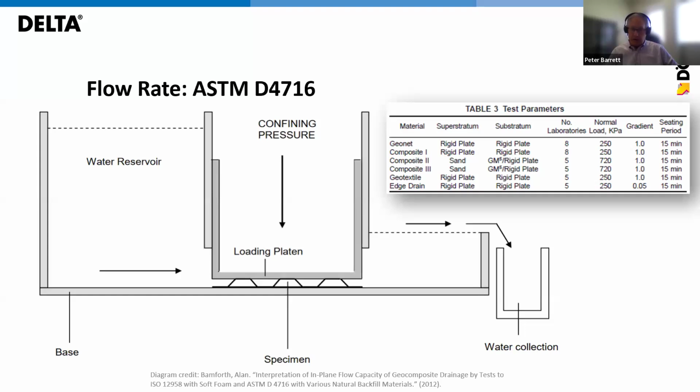That will put a load on the dimples, but not on the geotextile. That's not very representative of typical installation conditions. Most of us do not put a drain board on a concrete wall and then put something rigid like perhaps another concrete wall against it. Not that that's unheard of, it's just not very common.